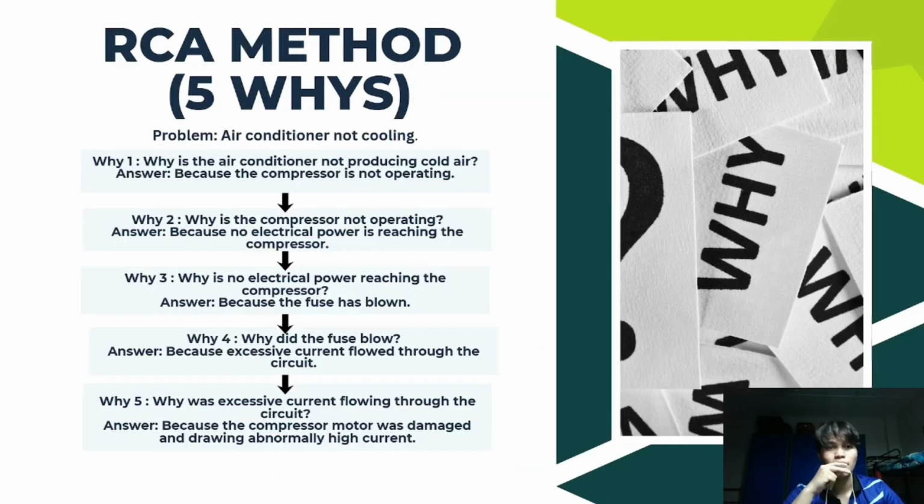Alright, so next I applied the 5 whys technique, which is one of the most commonly used root cause analysis techniques. The idea behind this technique is to repeatedly ask the question why, until the actual root cause is identified. So the first question is, why is the air conditioner not producing cold air? The answer is because the compressor is not operating.